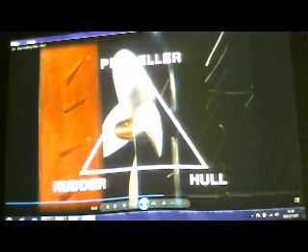How do these interactions between propeller, hull and rudder influence a stopping maneuver? There are several maneuvers which can be used to slow or stop a ship. Crash stop, when the propeller is put to full astern from full ahead, can be used. A considerable loss of rudder effectiveness and a large transverse thrust occur, resulting in a pronounced turn to starboard. This turn can result in a large change from initial heading and takes the ship well off the intended course.